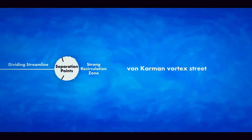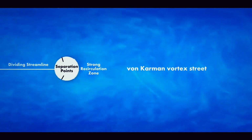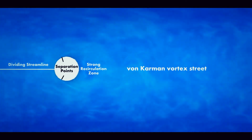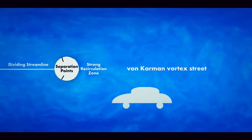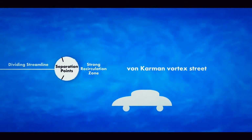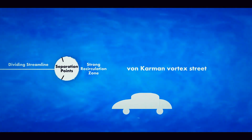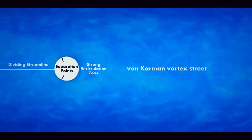And then further downstream we have the von Karman vortex street where there's a lot of oscillations, and that leads to different types of forcing and instability that can occur downstream. That's why if you're traveling down the highway and you're behind a semi-trailer truck, you will find your car has side force going side to side, and it's due to that vortex street behind the semi-trailer truck.